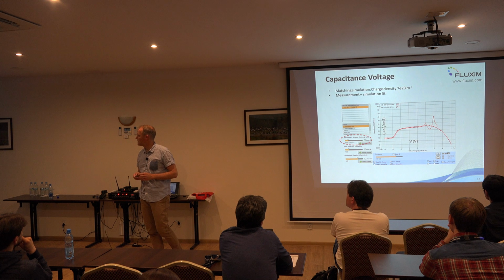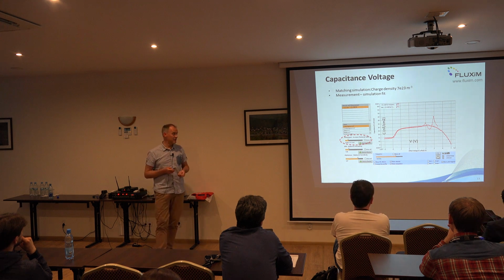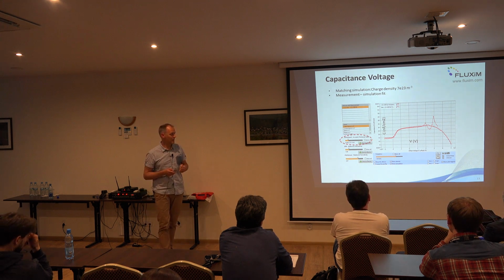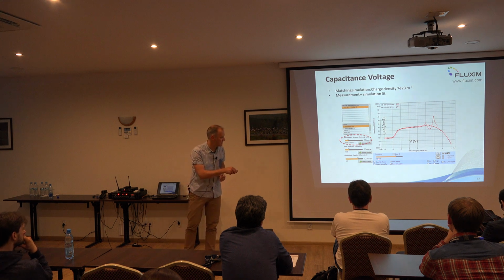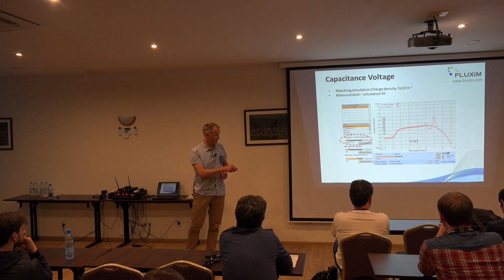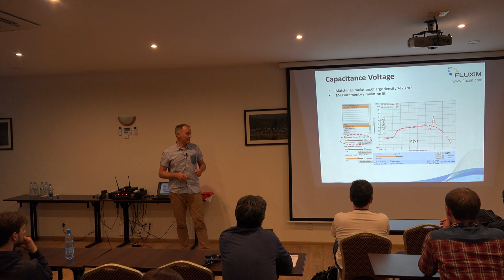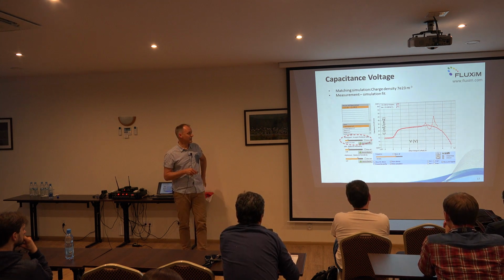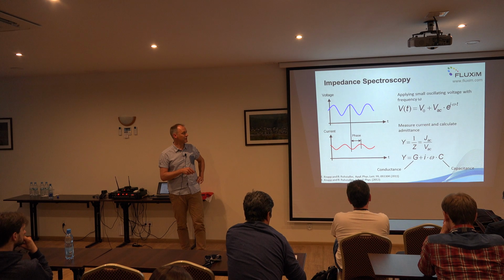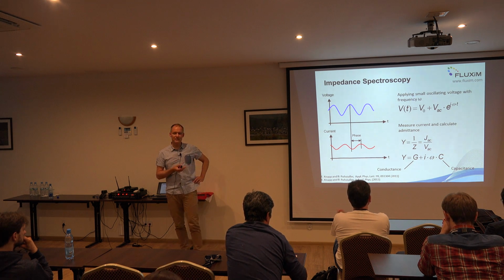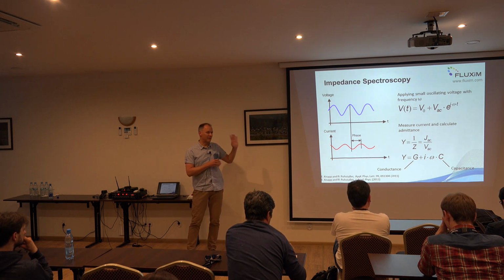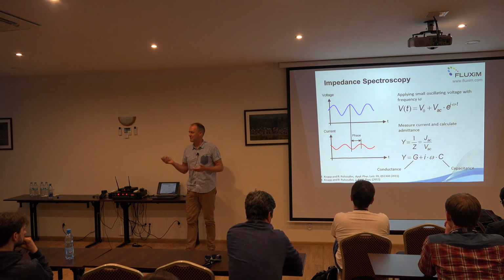That's capacitance versus voltage for a fixed frequency. Here 1 kilohertz was used as the frequency for this measurement. Instead of keeping the frequency fixed and sweeping voltage, we can also do a frequency sweep. So this is now the first experimental type that I'm going to explain.